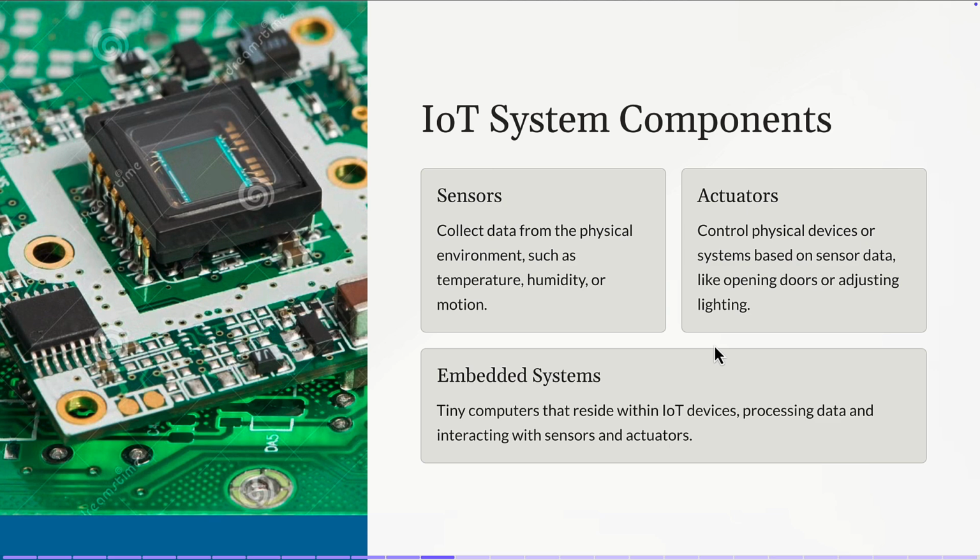But the problem of ZigBee is it only supports a very small amount of data, low bandwidth. It cannot send huge data like images. And this is sufficient because in IoT devices, we usually send a small number of bytes, so we don't need high bandwidth. And there is a problem of latency because usually these devices are in low power mode, so they are prone to more latency in processing the bits that will be sent over the network. Is it clear? Okay.